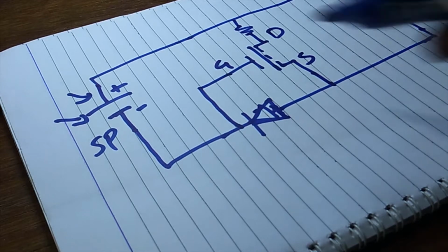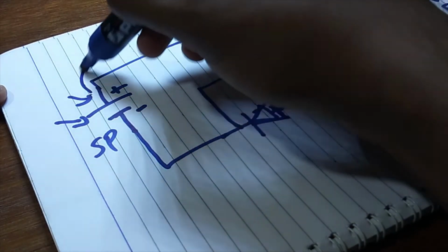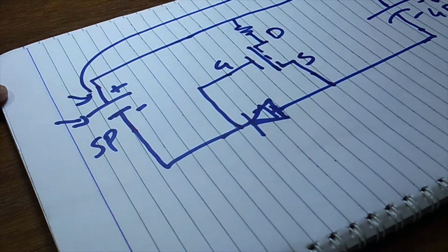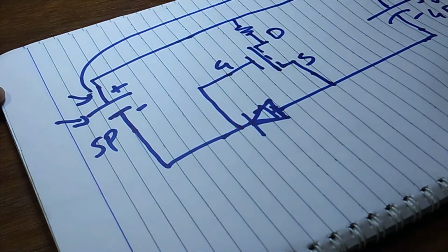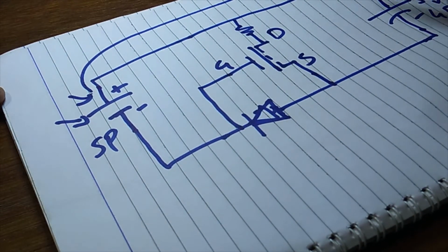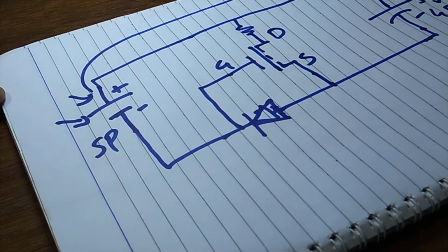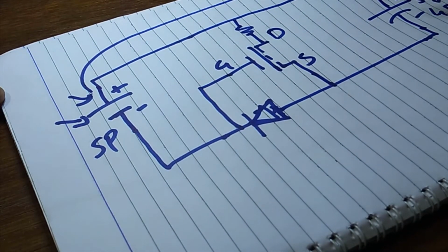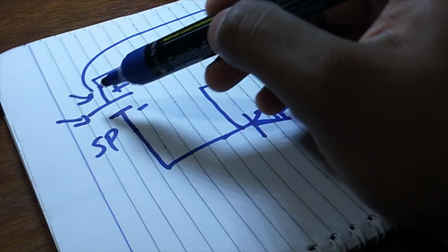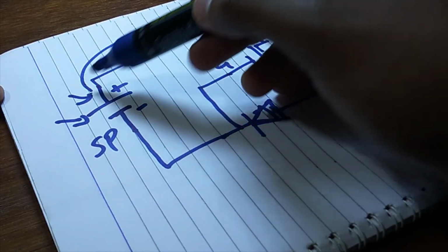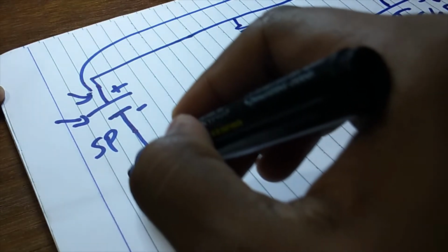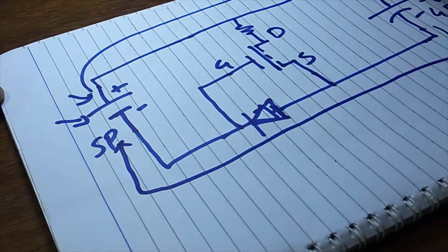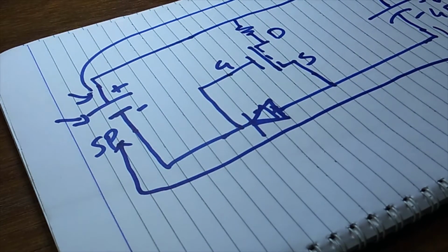What happens is, in the normal flow of electrons, this is going to go and charge the supercapacitor. So the current flow is normally going to be this way, and the current will start flowing through the circuit. Let's say the supercapacitor is at 0 volts. In such a case, the solar panel starts receiving some kind of sunlight. It starts building up voltage, and then the current flows through the supercapacitor, through the diode, and then goes back again. So you have an unrestricted path for the current to flow when the solar panel is active, or when there is some light from the sun.